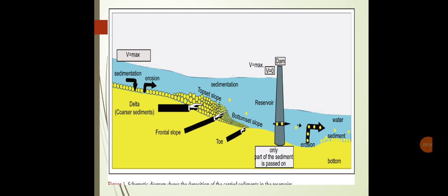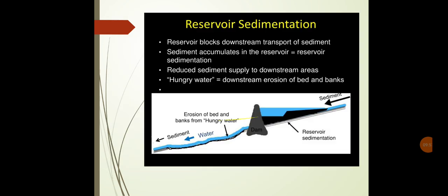Only a part of the sediment is passed through the river sluice. Most of the other particles will be deposited in our dam itself. Smaller particles only, clay and silt particles, are carried through the reservoir sluice. Because our storage structure is huge, if you are stagnating that water, definitely your particles will be deposited. Only a small quantity will be moved through this reservoir.